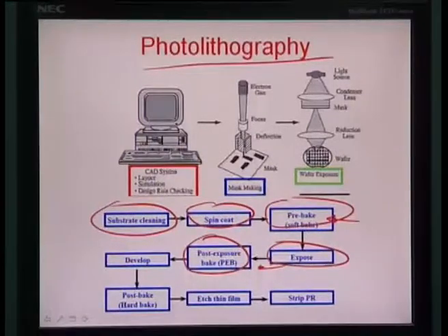Exposure, however, can be pronounced and catalyzed further by application of heat, because heat enhances the diffusion process in the way that the photoacid generator would go through, and therefore the post exposure bake is highly needed for this kind of situation.